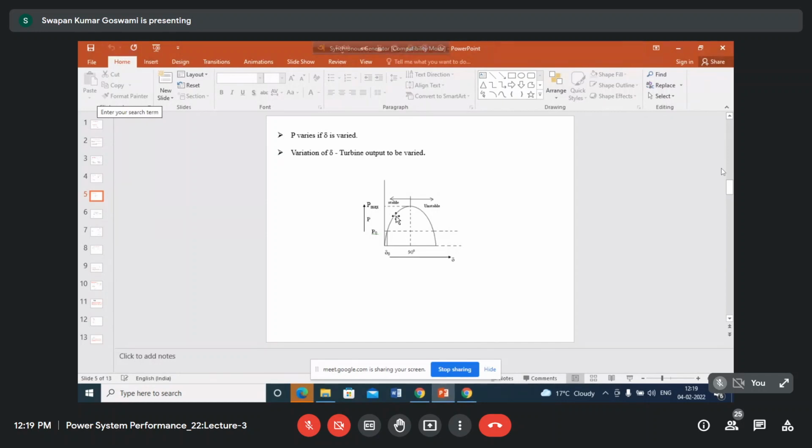In this way, there will be oscillation of the rotor speed, and finally, when the generator again gets synchronous speed, it will be delivering more power than it was delivering previously, because by this time there was an increase in the opening of the steam valve. Say previously this was the power input, and now the power input increases, it is somewhere here. If it is here, then what will happen? The generator will oscillate around this new position of P, and finally it will be stable here.